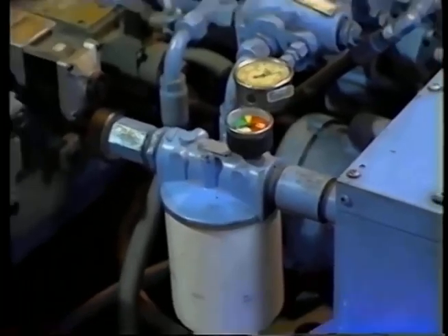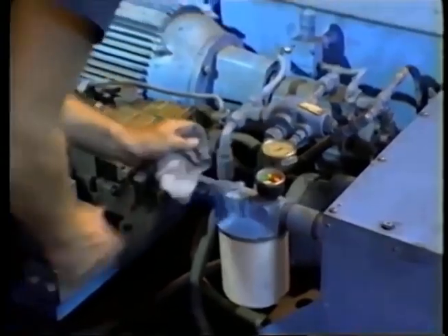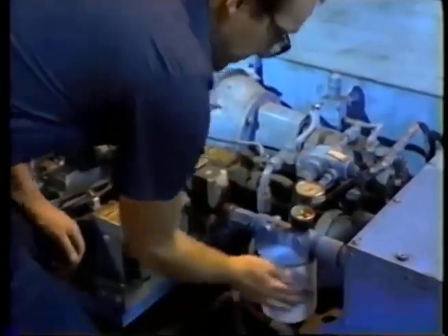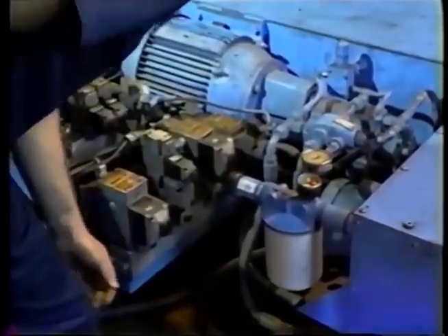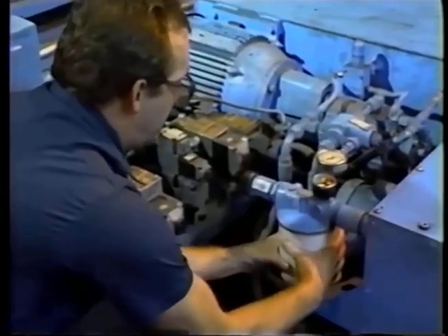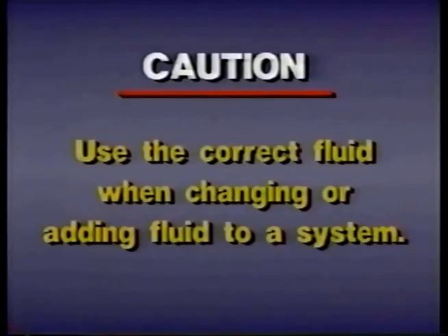Inspect your system's fluid frequently for contamination and keep any filters serviced regularly. If the filter is being bypassed, it needs to be cleaned or replaced. One final note of caution: make sure you're using the right fluid when changing or adding fluid to a system. Because different additives may have been used, different brands of fluid may not be interchangeable.